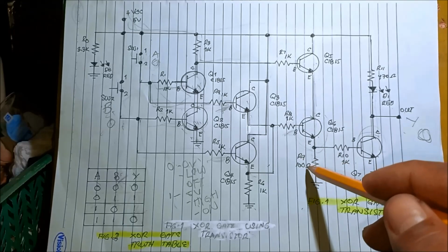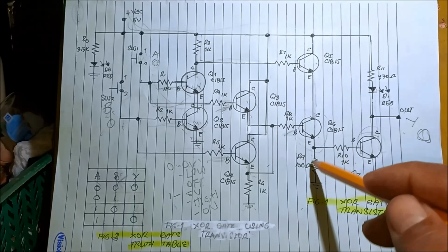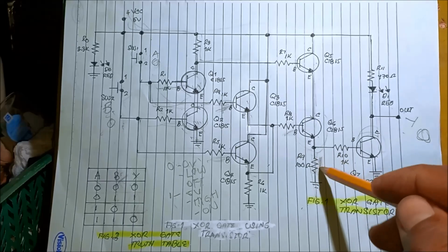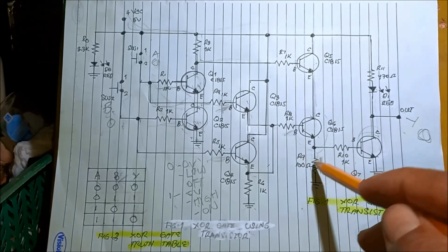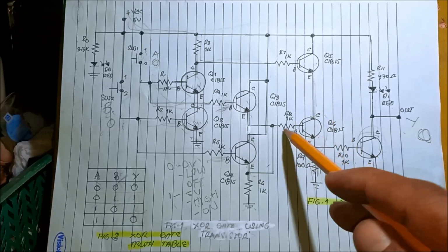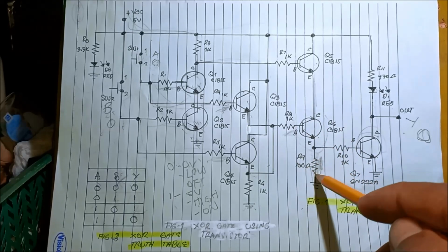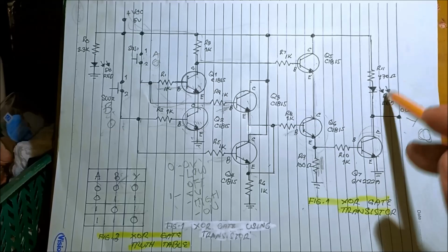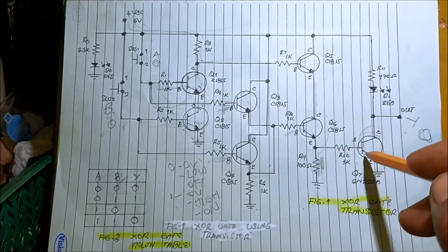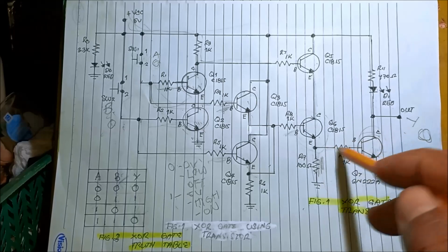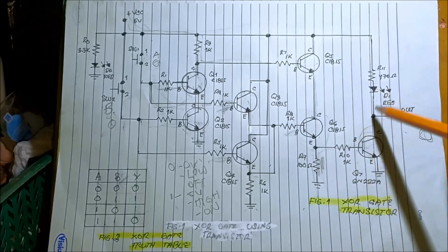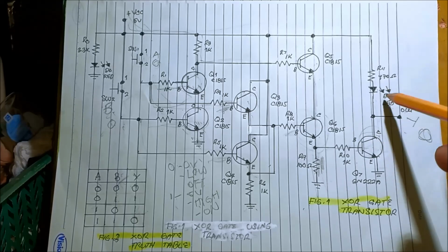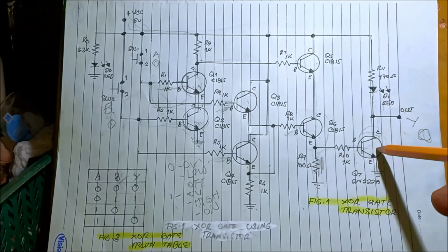This is a current sense resistor, an emitter follower type, because all the current flows into R9 100 ohms. With the use of the driver for the LED, a common open collector output, it helps to have a constant current source for the LED.